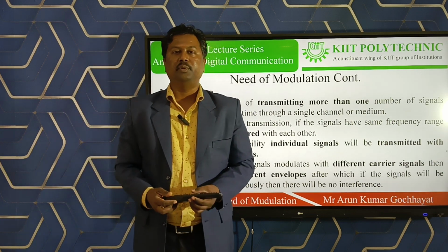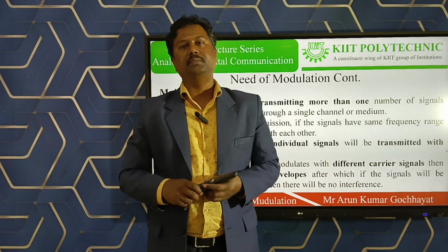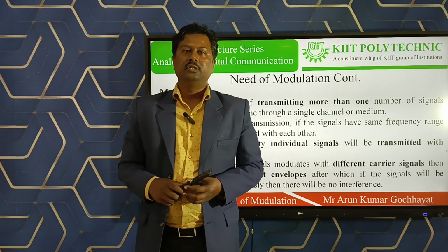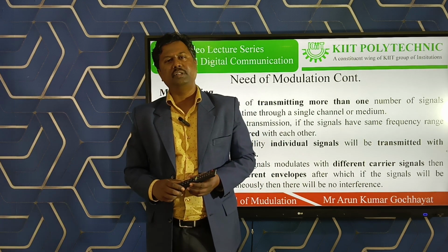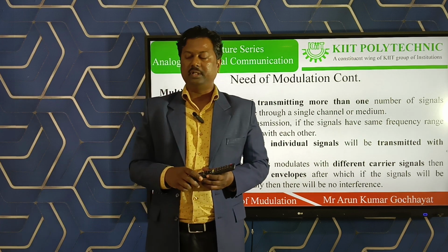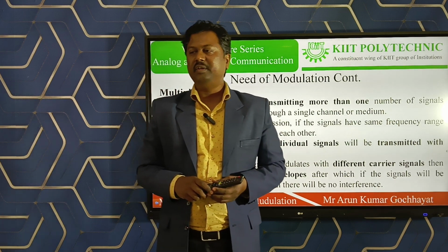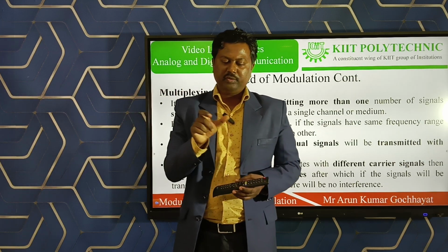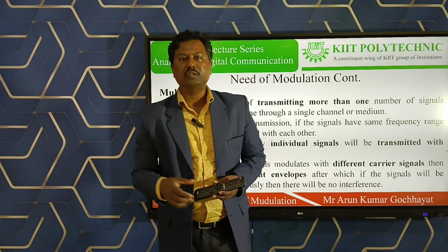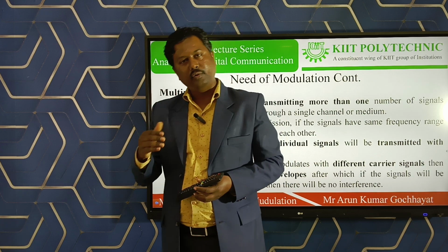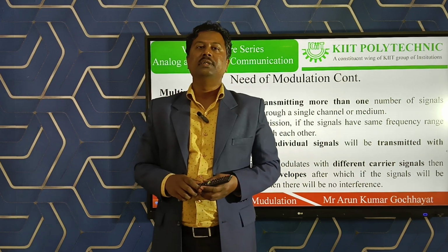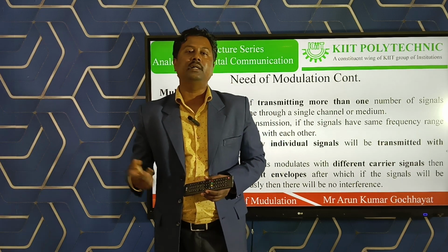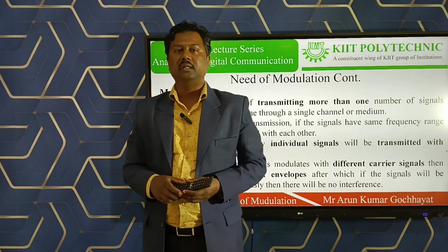Last but not the least, the last point is multiplexing. It is a process of transmission of multiple message signals simultaneously through a single channel. Why is it required? Because in modern communication systems, when we convert a message signal into digital form, we convert it into a train of pulses. Between two pulses, there will be a vacant space, and that vacant space can be used during transmission by other sources or other message signals also. So those vacant spaces of the channel can be utilized simultaneously by any other source or signal, and that is called multiplexing.